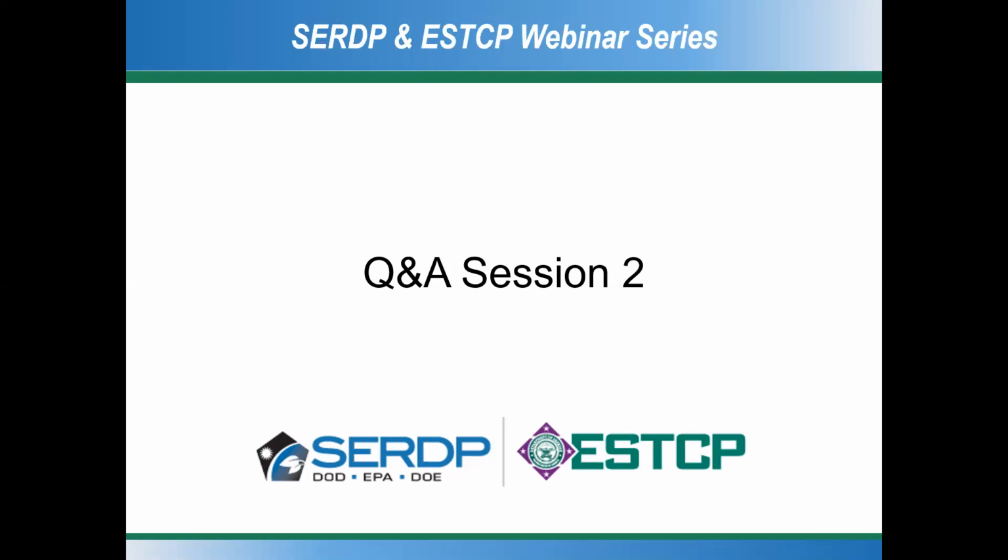Okay, thank you. And does it work just as well for injection grouting then to use just one very long screen instead? That's a good question, and I think our thought process on this has changed a bit. Because of this heterogeneity rule of thumb, the original idea was that if we could just clog up that small cross section with a long screen, for instance, that we would get the majority of groundwater flow.